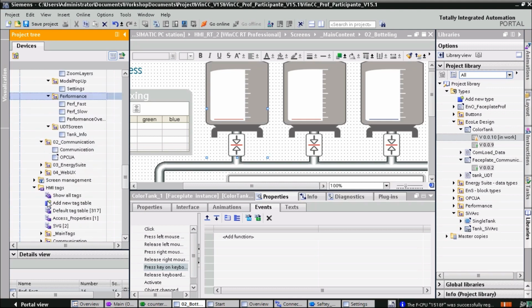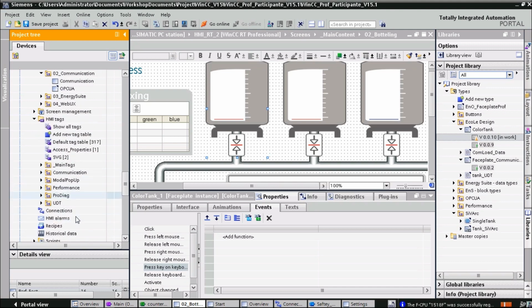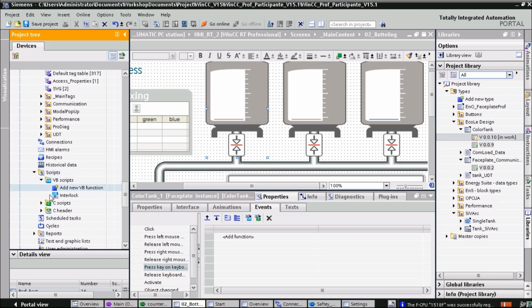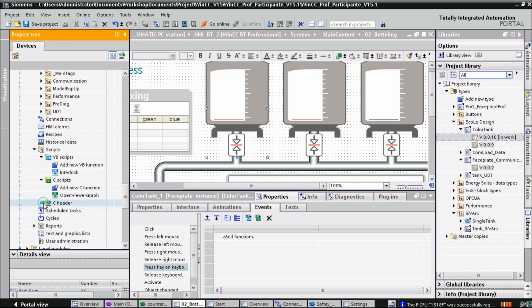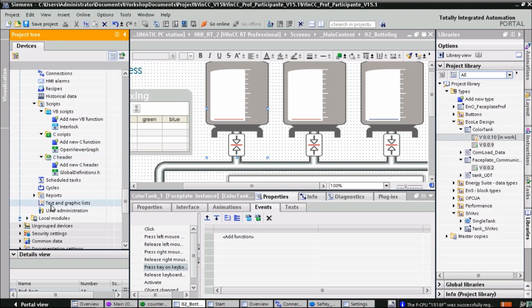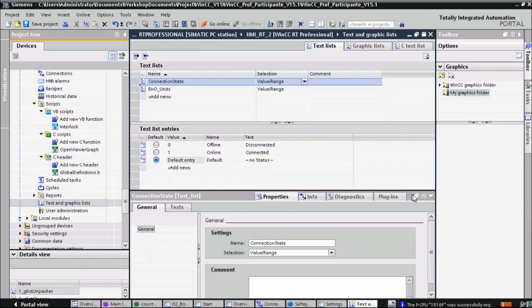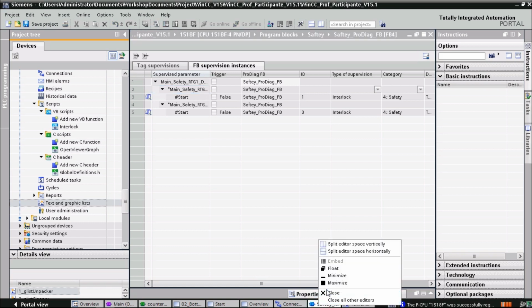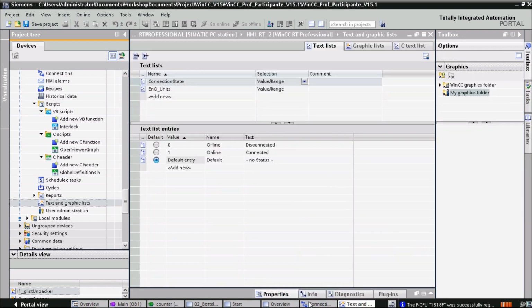One other thing, and I think that's also mentioned in the next hands-on, what I want to show is, because we had everything regarding UDTs and structures in WinCC 7.5 yesterday, you are also able to use UDTs for your faceplates in TIA Portal. For example, I don't want to show the valve status in the I/O field. I want to show my actual content in the tank. I'm just going to switch back to the properties here. I do have right now my process value of my I/O field, which is linked to the outside world, to my properties of the faceplate. And I do have here, for my valve state, right now an integer attached, but I can also change this data type here.